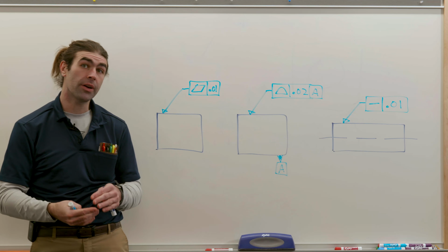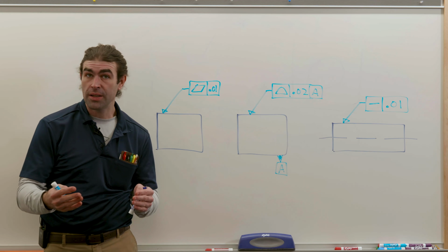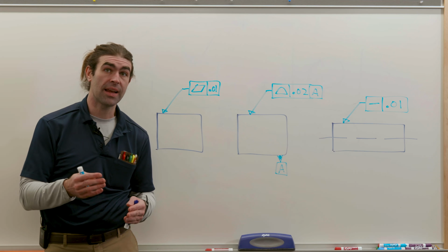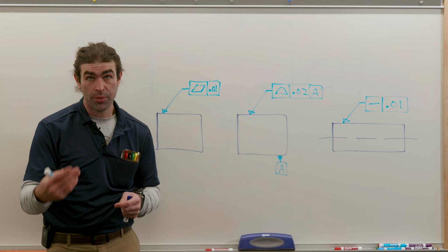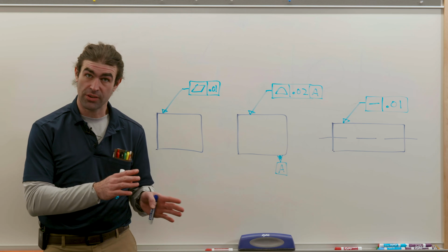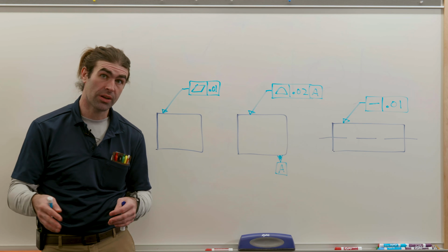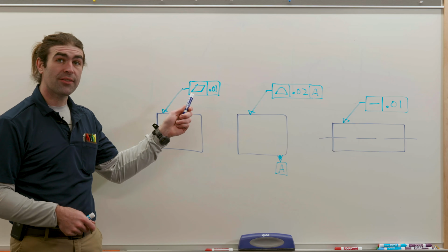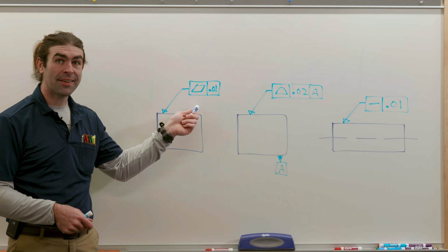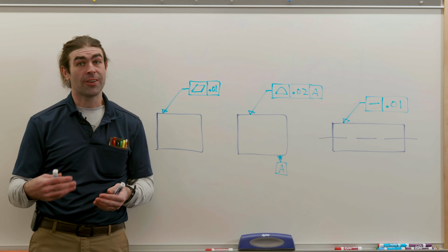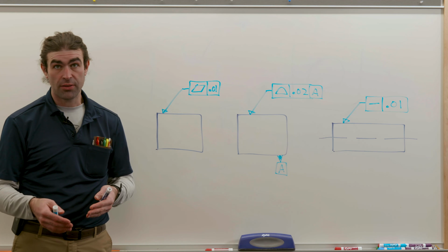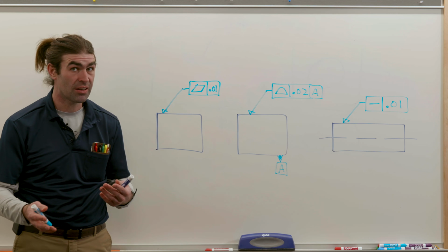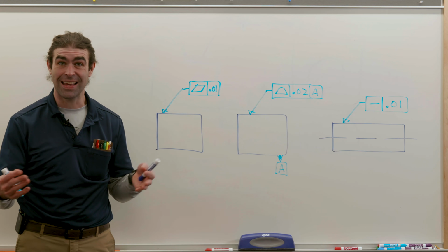So feature control frames differ depending on how they're applied, what geometric characteristic is applying, and how many datums there are. Now, there's more videos I've made about this, specifically the different kinds of geometric characteristic symbols, but let's just talk about a few. First is form tolerances, like flatness, which typically don't or never have a datum reference. Because form tolerances only apply to individual features, there's never a need to relate them to anything else.